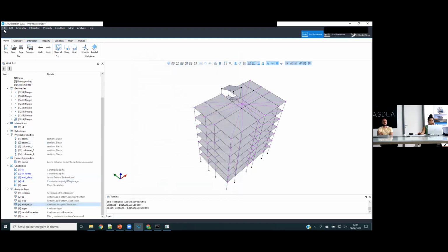Like specifically in the other example, the same time series that I've used as a load ramp in the gravity analysis, it's used in the displacement control analysis too. So it's like the same. Yeah, in the displacement control, no, actually, it doesn't use the ramp. You have to use the time series because the OpenSees commands require a time series, but it is not used. So it can have any shape, but the displacement control analysis will not follow that. It will not ask the load multiplier to the time series, but it will take the current pseudo time step as the load multiplier. Is it clear?